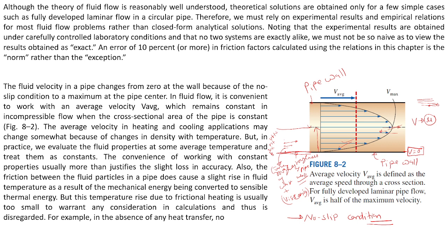Now moving ahead, here one thing is also important. In the generalized formulas you have seen everywhere, up to most undergraduate levels, we use the average velocity with some correction factors, which you already know about, alpha and beta, the kinetic energy correction factor and the momentum correction factor.